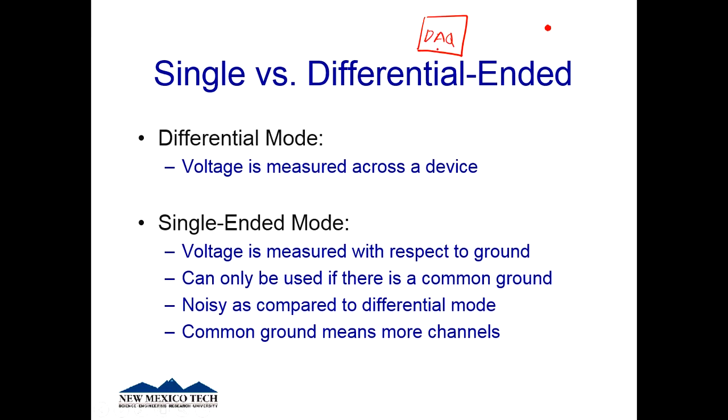If this was an in-person class, I'd be handing you a data acquisition unit for you to use in your labs, but I wasn't going to pass them out to everybody. But maybe this data acquisition unit has 4 channels. A single-ended connection would mean we could put 4 sensors out there.